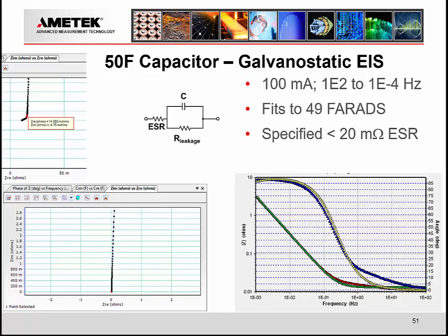Certainly, capacitor research benefits from electrochemical impedance spectroscopy as well. You can see a very simple Randles cell type design here that we have for modeling this data. Again, the equivalent series resistance in series with the value of the capacitor, in parallel with a leakage resistance due to leakage there. Here is the response, both in Nyquist and a fitted Bode plot. And we can see it resembles the impedance of a capacitor, right? As we decrease the frequency, the value of the impedance increases.